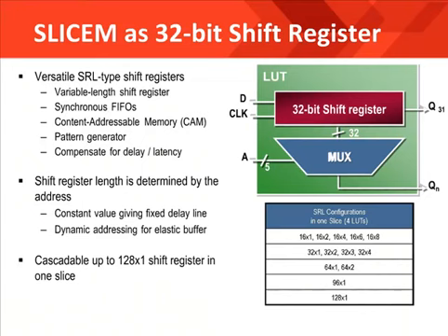The most challenging thing with this is that most customers don't realize that it is not loadable, has no reset functionality, and only offers serial in, serial out capability. So if you try to infer it with any of these behaviors, your synthesis tool will instead infer regular flip-flops.